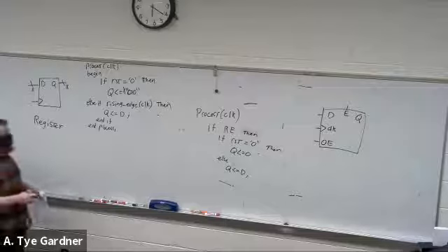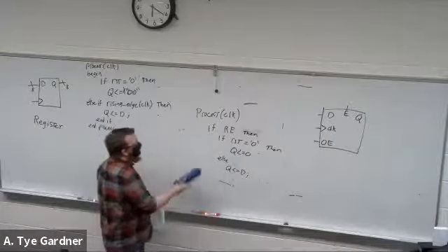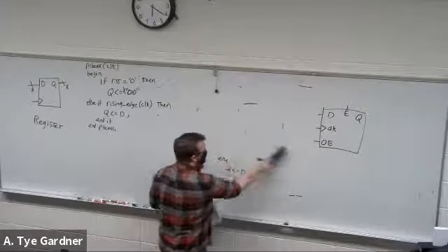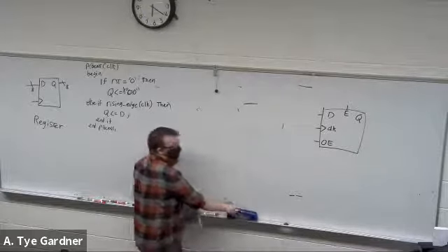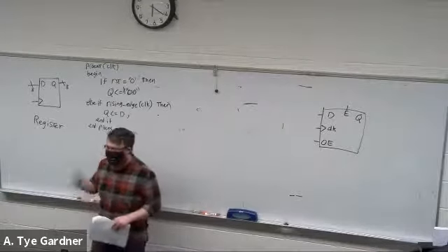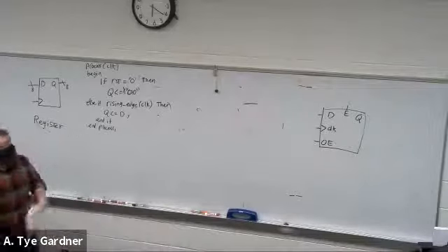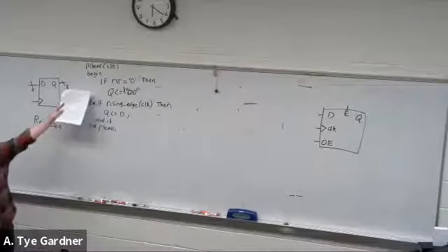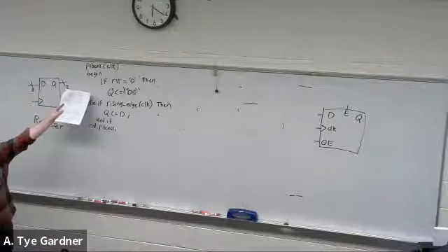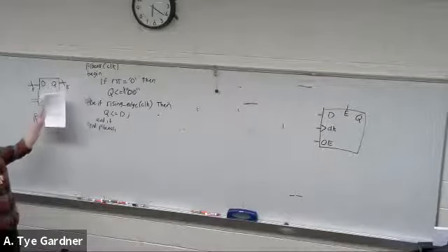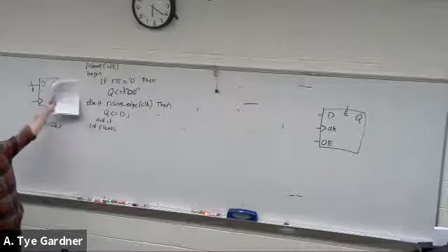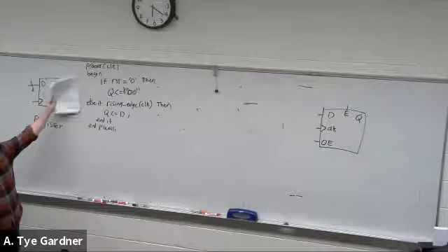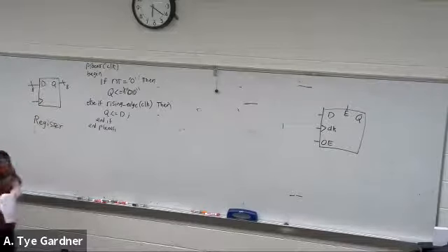Alternatively, if I want an asynchronous reset, which means that the reset happens no matter what, no matter when. This is almost there, right? Because this will activate on either the positive or falling edge. What do I have to do in order to make this code into a fully asynchronous reset?